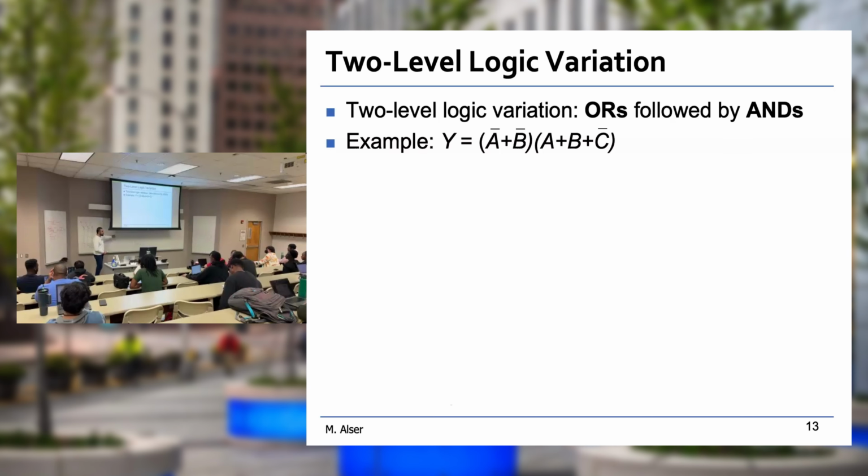Here should be AND gates. Okay? And then you could implement whatever it says over there. For example, A NOT. So you would go with A bar and then B bar. You connect them to OR gate. Let's in fact do it. I think it's better to erase it. Keep the things at the top.